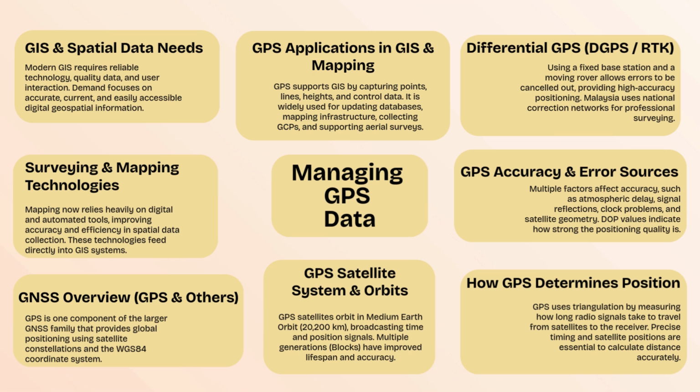On top of that, differential GPS and RTK use a base station and a rover to cancel errors. This gives very high accuracy. In Malaysia, networks like MyRTKnet and MASS are used for professional surveying.